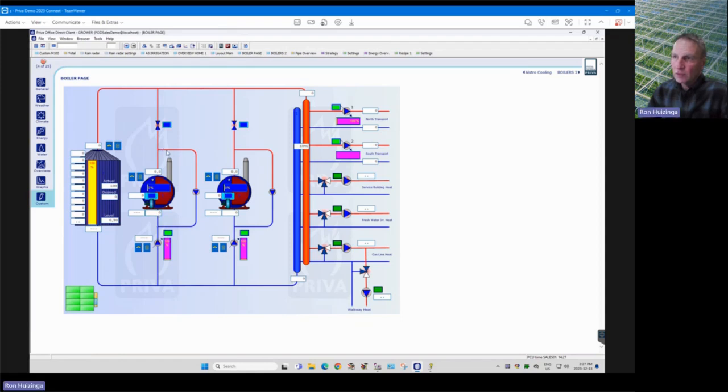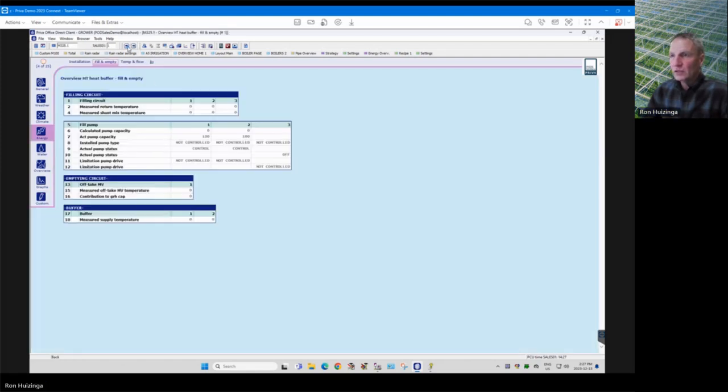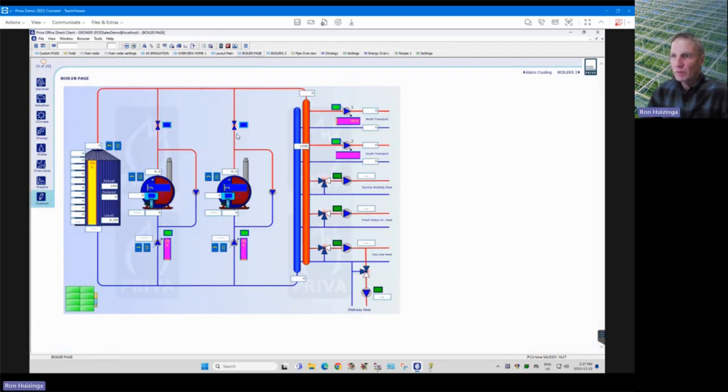So basically you have this temperature water being pumped around, 90 Celsius coming around, and then you have the return from the tank, let's say that's 40. And then this is a mix of the 90 and the 40. So it's a shunt mix temperature here. And basically that's going to be going into the back of the boiler at that point. So this is a little bit more to watch what's going on, that the computer is calculating the number. So if you have a geo page, we have a calculated and measured here. So quite often we put those numbers on this page so you can see what's happening.